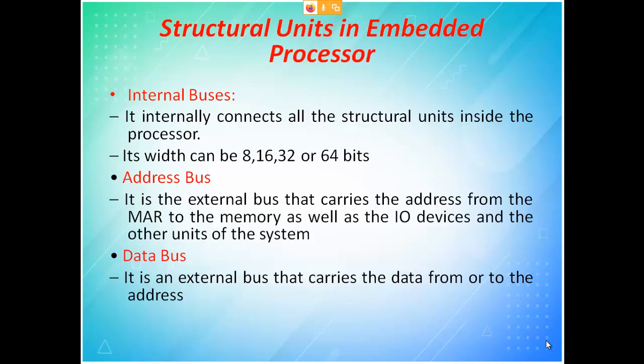Why we go parallel is, the advantage is a very fast way of communication compared to serial communication, but you require more number of lines. If it is 8-bit, we can understand that there are 8 lines running. If it is 16-bit, it is 16 lines running, and if it is 32, 32 lines. And nowadays in our motherboard, it has 64 lines of address bus. So a 64-bit address bus is indicating the address. Even today we will go only for 8-bit or 16-bit data lines, but only the address lines we will increase. I will tell why we are increasing the address bits.